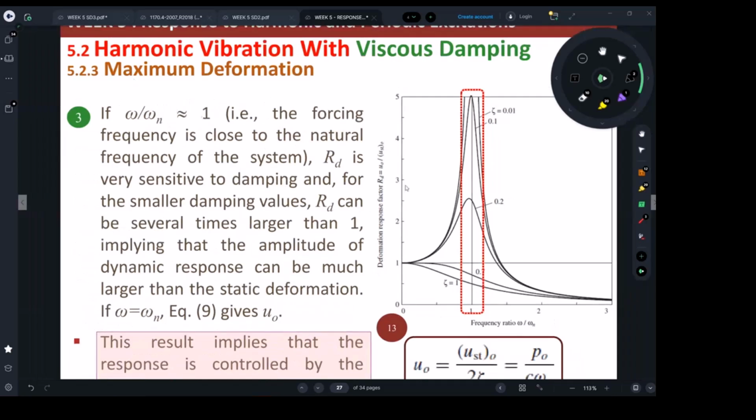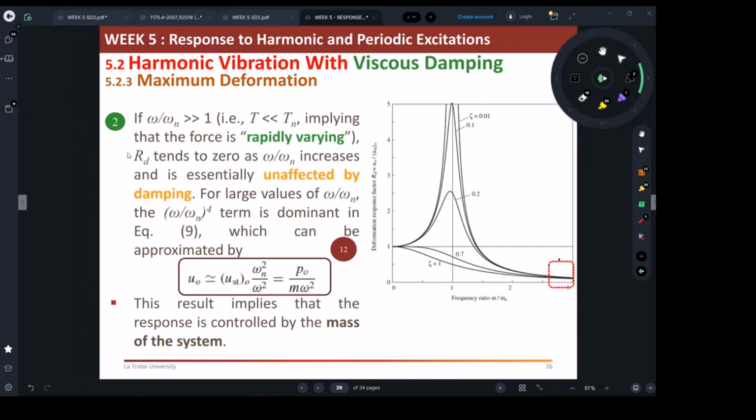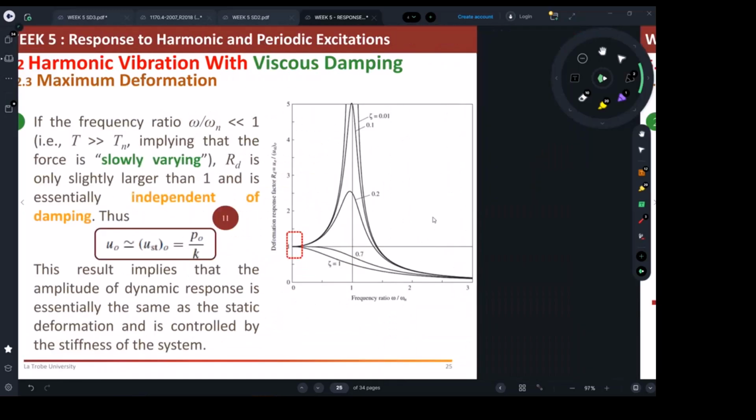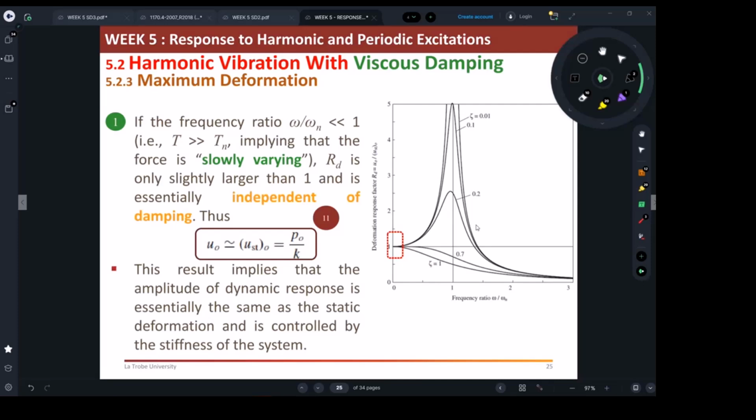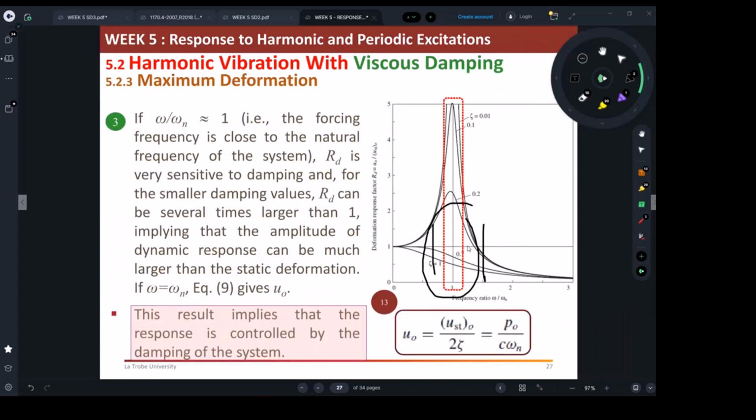But the good thing, it's always when you are close to 1, with your design, you can always play with it. You can always push your frequencies. You can control your design, but you cannot control them. It's difficult to remove the tram line or the train or stop an earthquake. You don't know how it's going to be coming. But you can play with the structure itself. And your aim is to try to put it within this zone or this zone to prevent the resonance.